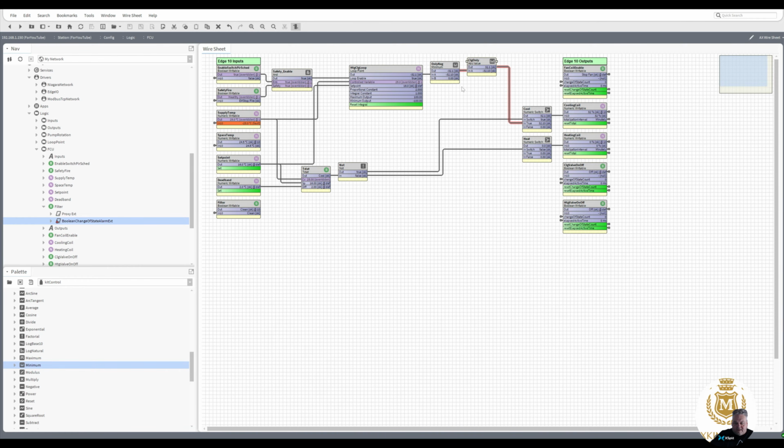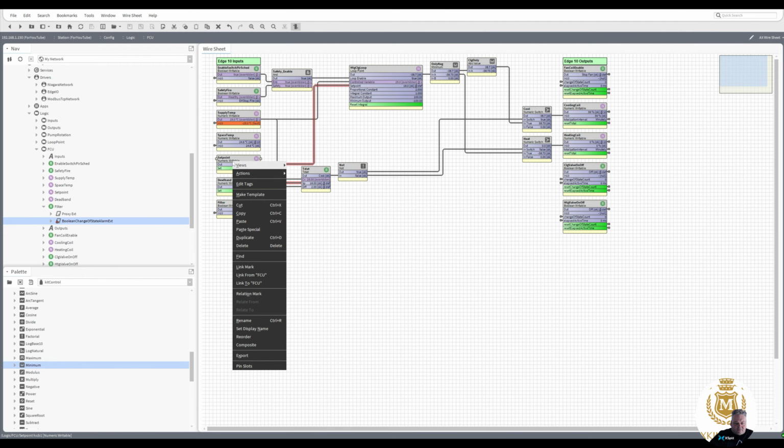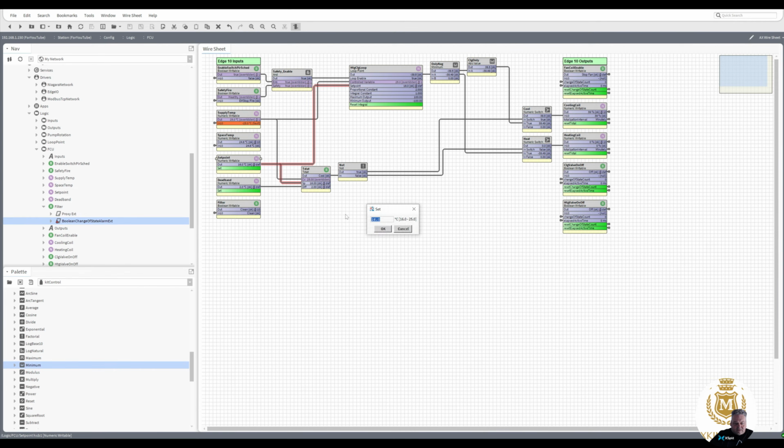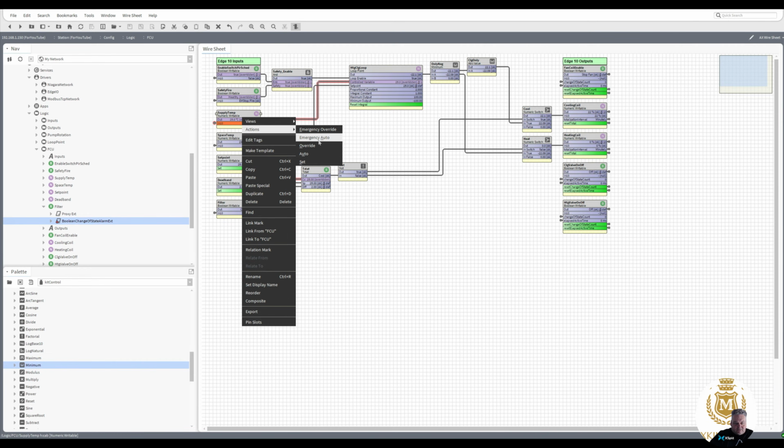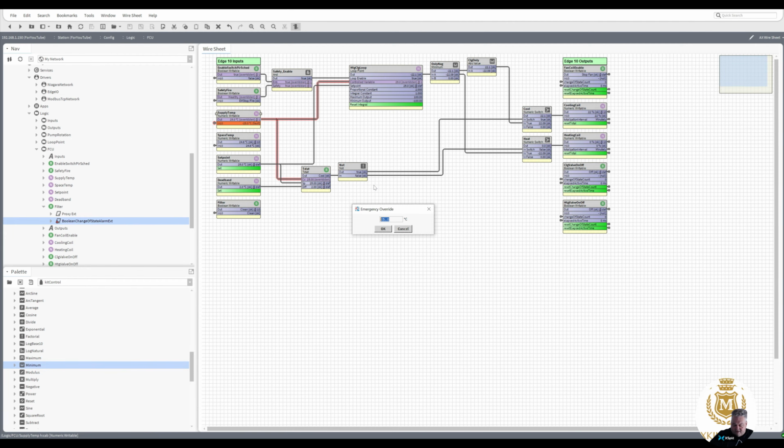And my heating coil will come directly from that, but it won't work because it's a minus value and we've not even switched it on anyway. So that's now opening the cooling coil. The heating coil is closed. Let's switch that over now. Set point, set that to 25 degrees. And let's override that to 16 degrees so it's really cold.